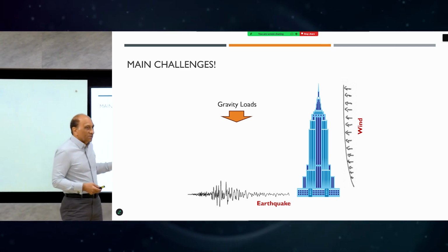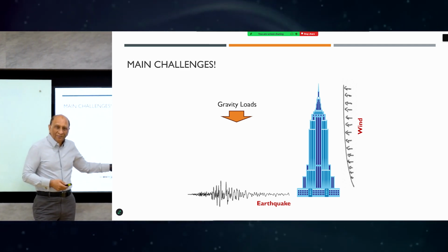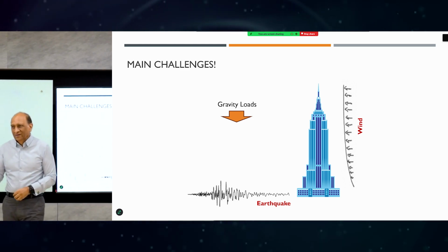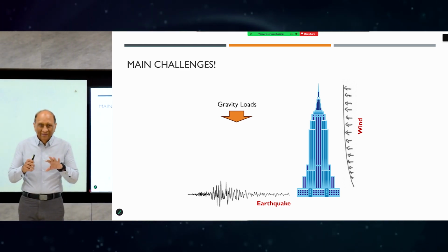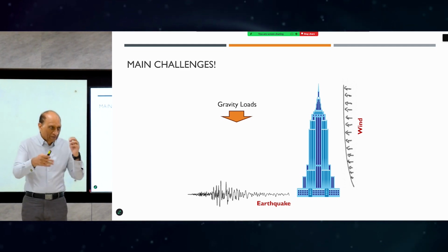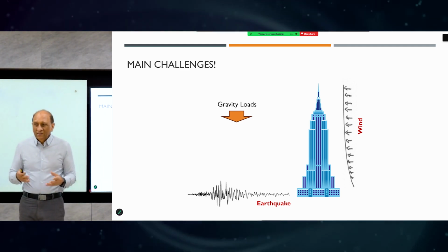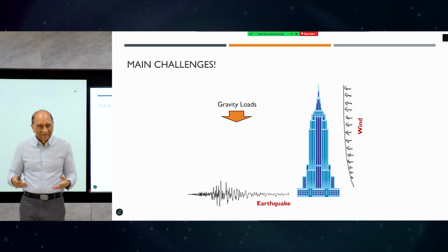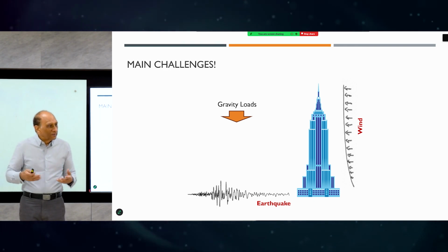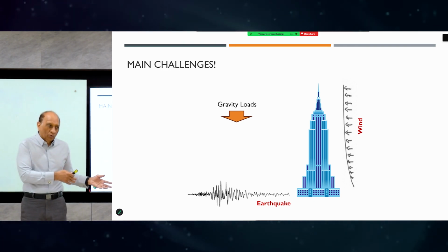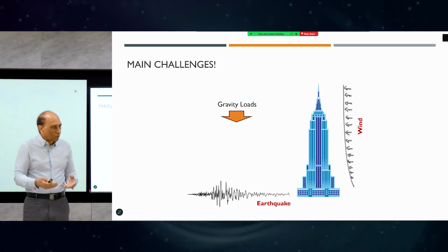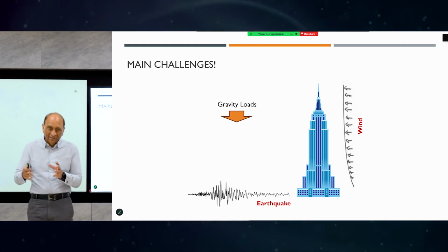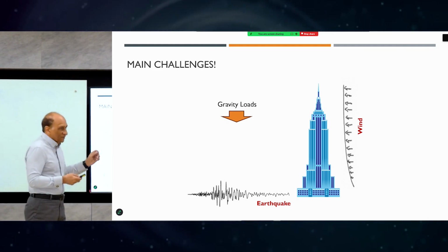Because we can control these two loads, it makes it even harder, because the loads are not constant anymore. Loads will depend on the structure that you are trying to model. So unlike live load or dead load, which are kind of constant, these loads are generated by the structure's form, stiffness, and its own behavior. They interact with the loads. So not only is the section not known, the load is also not known because it can be changed after you finish the design. And that is the key difference between tall buildings and smaller buildings.